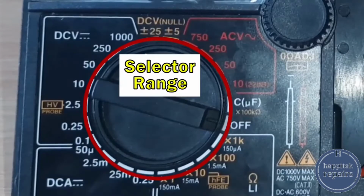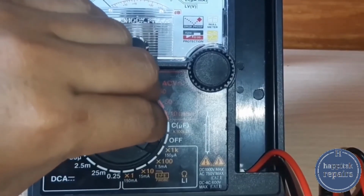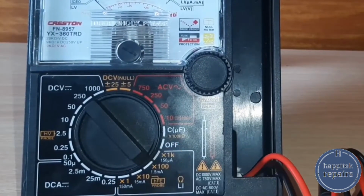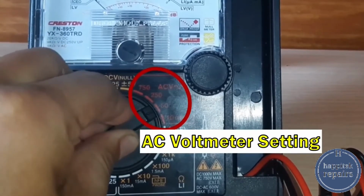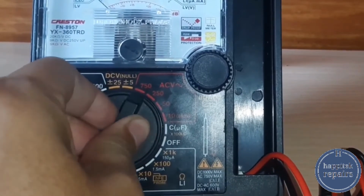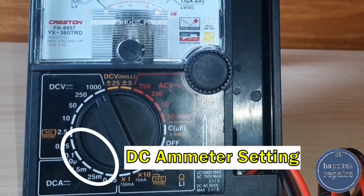Meanwhile, this part is called the selector range. It is intended to select the proper setting for the intended measurement. For example, if we wish to use the ohmmeter, all we have to do is point it to the ohmmeter setting. If you want to use the AC voltmeter, just rotate the selector range to this part. When using the DC voltmeter, you rotate the selector range here. When I use the ammeter, I set the selector to ammeter on this area.